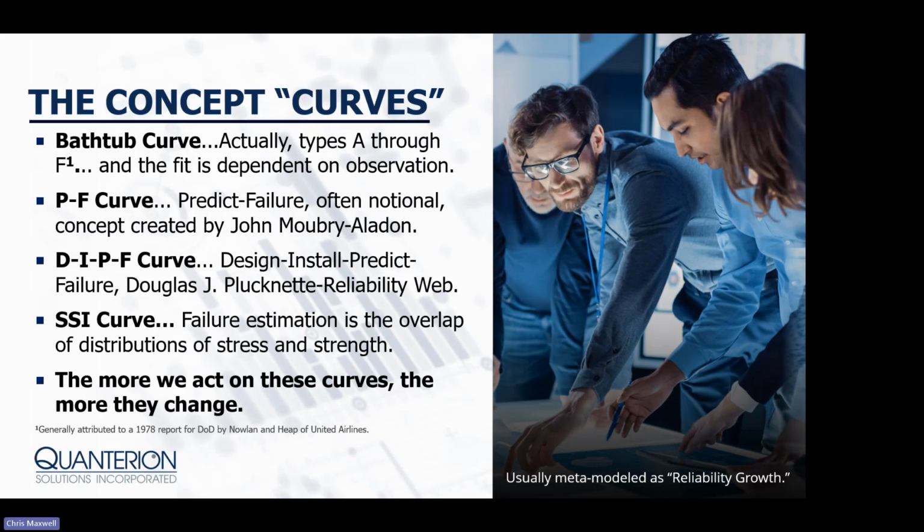Bathtub curves are a classic reliability concept, often over-applied, as in generally people always talk about the bathtub curve, but there was a study done by United Airlines that classified what they called the A through F versions of the curves, which is the actual classic bathtub is a relatively low percentage of the time.